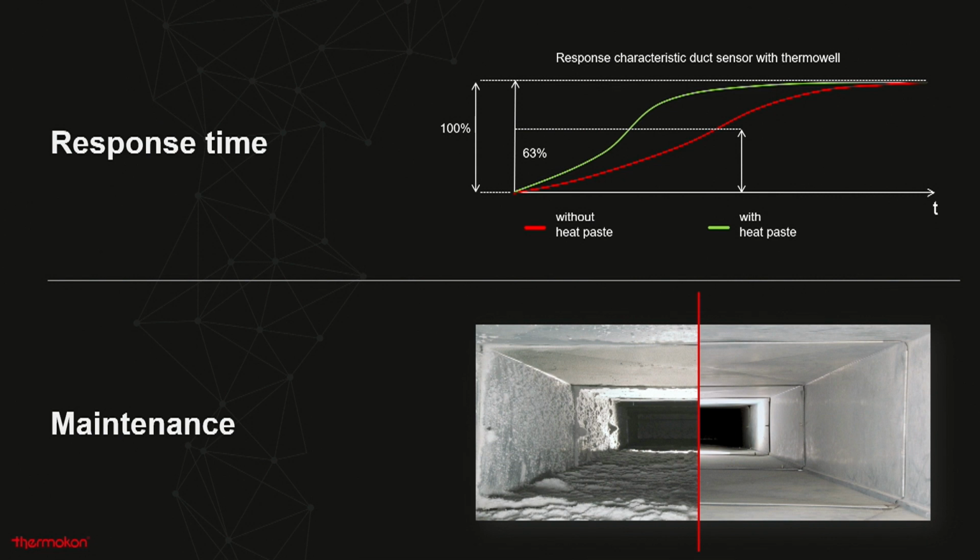we see how the response time is decreased by this. And if your measurement is especially taking place at this point, then you have a deviation in the measurement value, which can be hindered by having more awareness. And the picture below, I guess it speaks for itself. That's something we often see on construction sites or within projects. And I guess it's quite sure that the sensor mounted within this duct would never give an accurate measurement value because of all the dust that's inside.